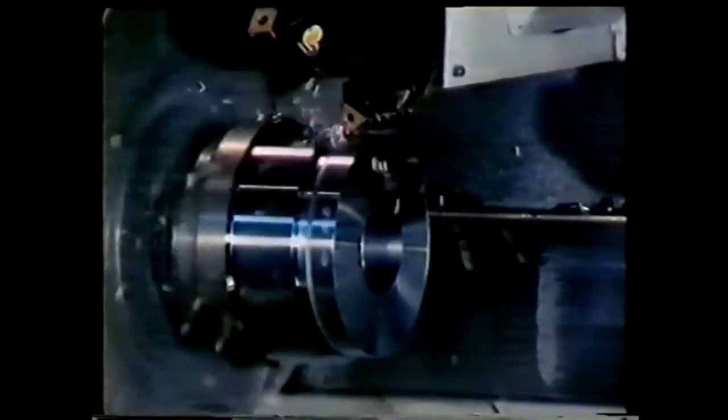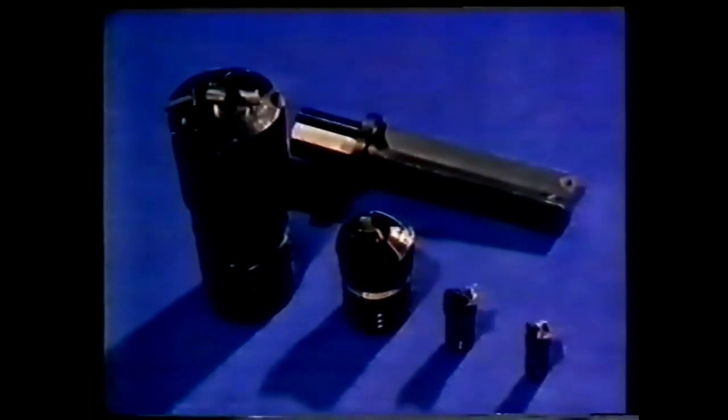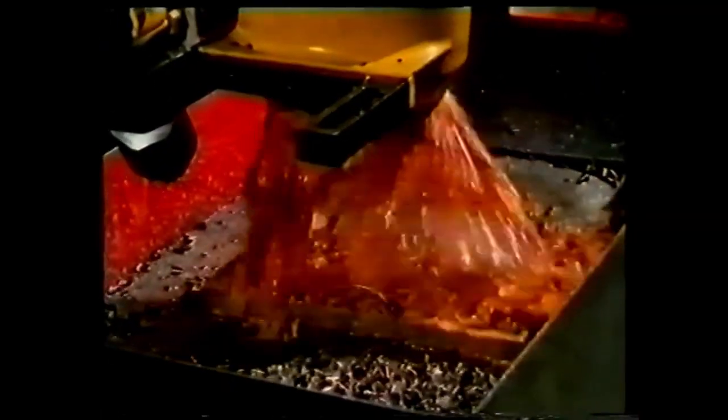Tungsten carbide is also used for milling cutters on the same range of materials and using similar inserts. This particular example proves that the right insert has no difficulty dealing with an intermittent cut at high feed rates. When used for drilling, carbides, due to their composition, can't be placed centrally on the drill head. If they were, they wouldn't last long. This is easily overcome by offsetting the tips. Usually the drill head is hollow, allowing the swarf to pass up the center of the tool and be ejected behind the drilling equipment.